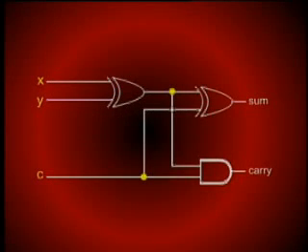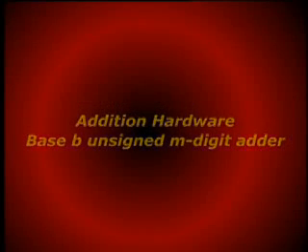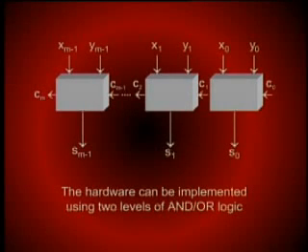Now, the next implementation incorporates the previous carry as well. And you see there is one additional gate. So this would be a complete full adder with input X, Y, and the previous carry, which we just call in this case Cj, and next sum is Sj, and the carry is C(j+1). So we could further add up more stages and make it an m-bit adder with the stages in cascade one after the other. Now this slide shows the cascading of different stages.